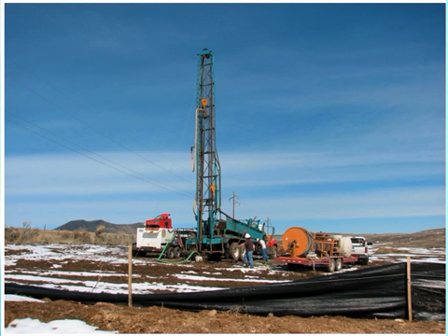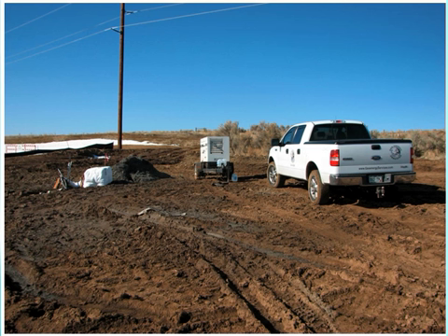So if you specify a 300-foot test borehole, then that means the rest of the Borefield is probably going to have to be designed for 300-foot depths. Now, there could be some variations as to why you might need to change that, but if you're going to use these TC test results for ground thermal conductivity and ground temperature, you better be careful if you change the depth of the design moving forward. Certainly, you don't want to take 300-foot test borehole data and then design a 250-foot borehole system, because that is going to put you in a lot of trouble.